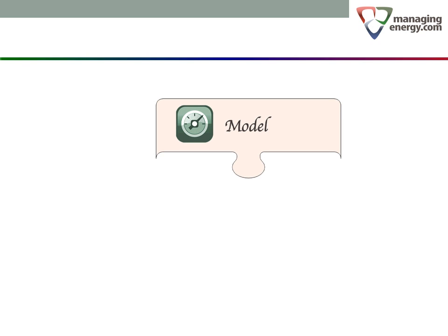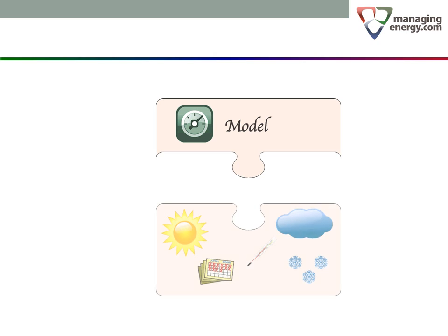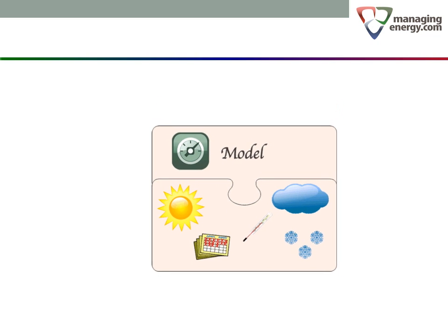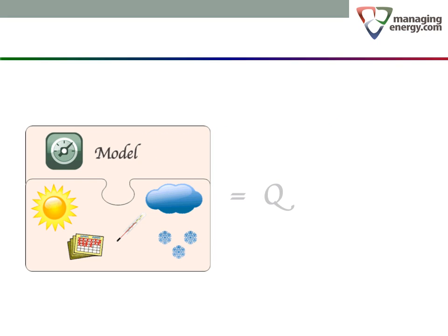Looking at the modeling process another way, we can think of it as two information packages. The constants T, H, and C are properties of the metered service. They define the model for consumption at that meter. The variables X, Y, and Z are values taken from the reading period. They are the inputs to the model. Combining both information packages, the model defining the metered service, and the conditions during the metered period, we can calculate Q, the expected consumption over the metered period.